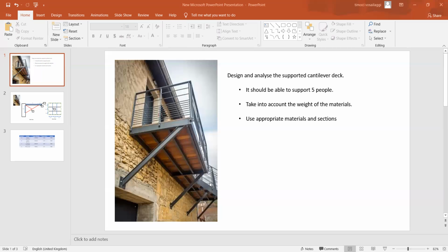That's the whole reason why, when we're talking about trusses, we say that the worst deformation will happen at the center, at the distance in between the 2 supports. That's going to be the worst case scenario. So you always try and apply the maximum load at that worst place, and design so that it's safe there, so that you know it'll be safe in any other way that you load it.